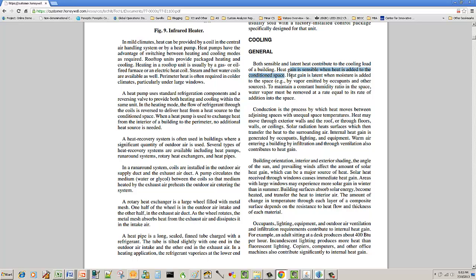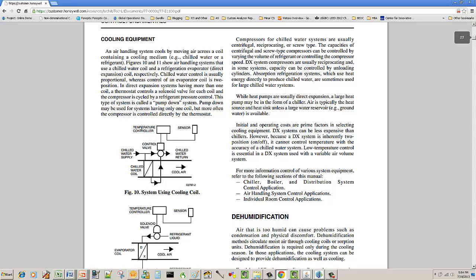What does that mean? Okay. Sensible, right? That's just adding BTUs. Like moisture's added, etc. So in the humid space, you must take the humidity out, right? Now, that is your sensible, and latent is an actual change. That's an actual state change. So, for example, if I convert steam to hot water, I can have a lot of BTUs because I'm doing a latent change instead of a sensible change. Alright, so let's move into cooling equipment.